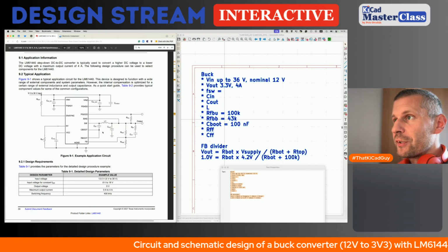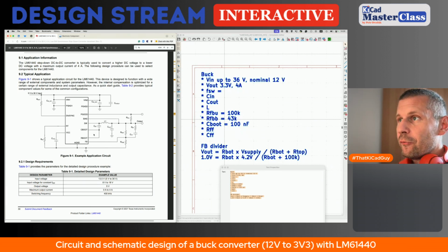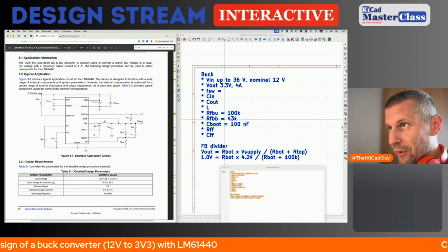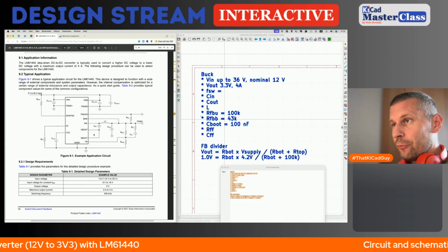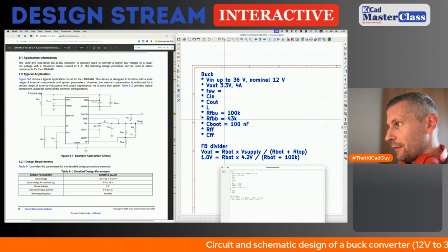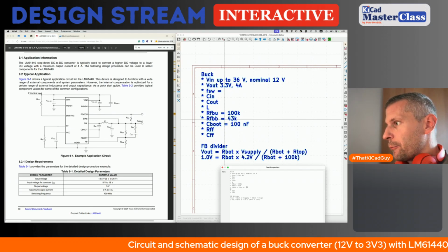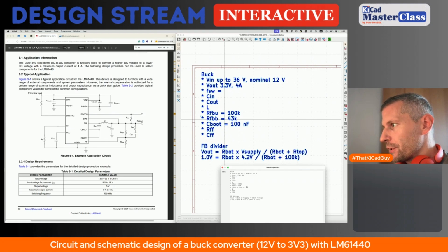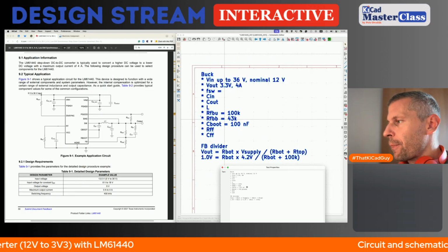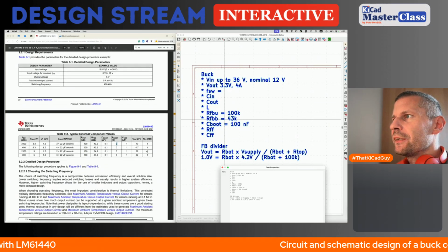The switch node is very sensitive, and everything involved in switching, the bootstrap capacitor and bootstrap circuit, is definitely involved in switching. So I'm adding the R boot below the C boot. So R boot will be 0 ohm, like a placeholder.